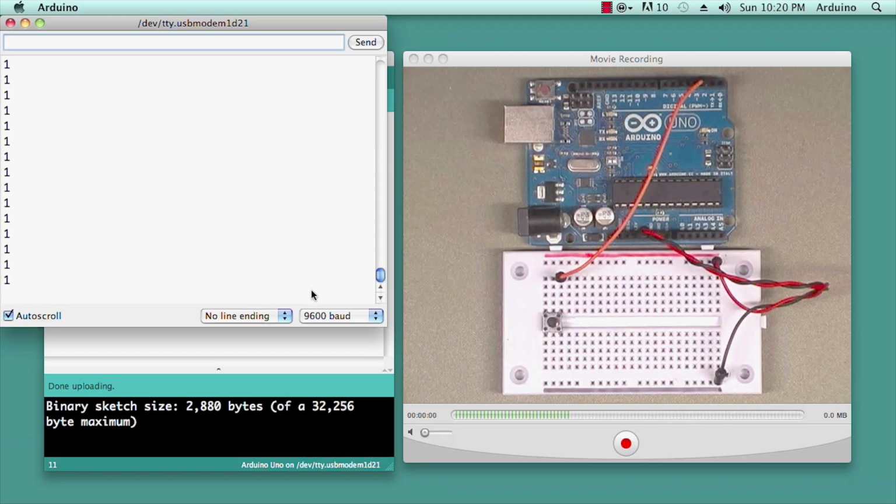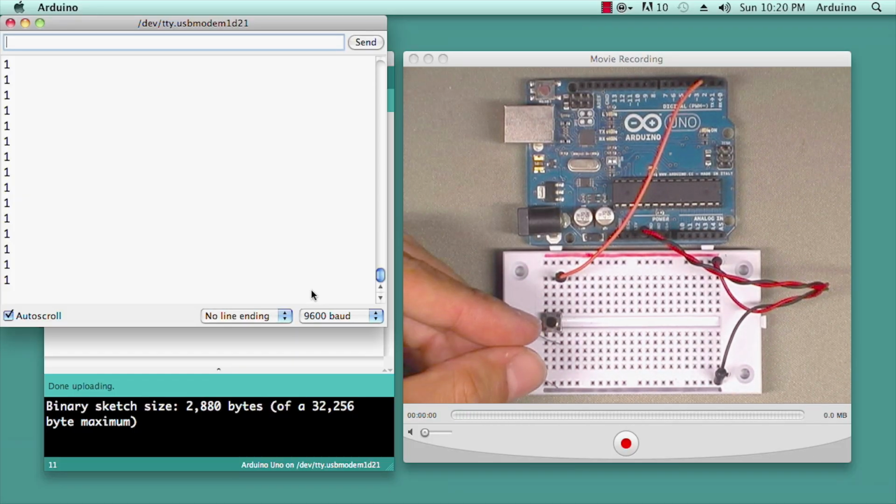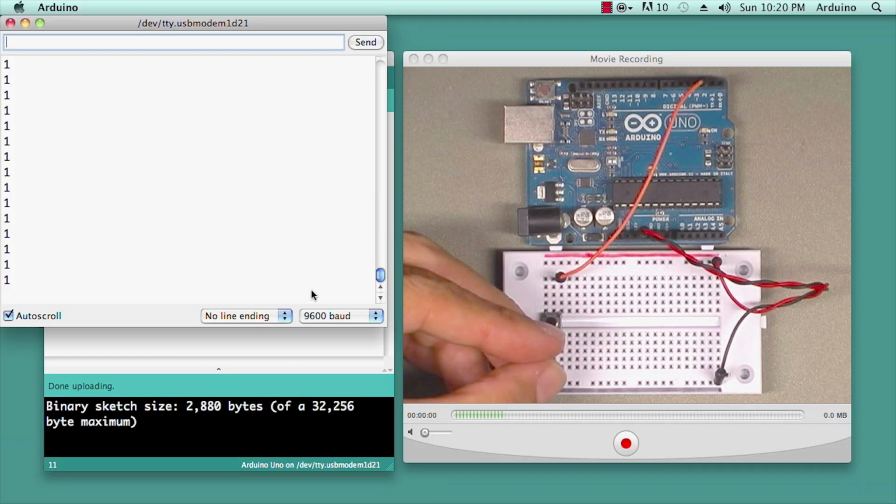And the purpose of that resistor is to ensure that there is always a connection to ground, which means with nothing else going on, our circuit is always going to show a 0, a grounded state. And here is our pull-down resistor. We call it pull-down because it's pulling the value down to 0 or down to ground. And this one is brown, black, and orange, which is a 10 kilo ohm. So it's a very high resistive value. And I can plug it in anywhere in this column and then down to the ground bus down below, like so.